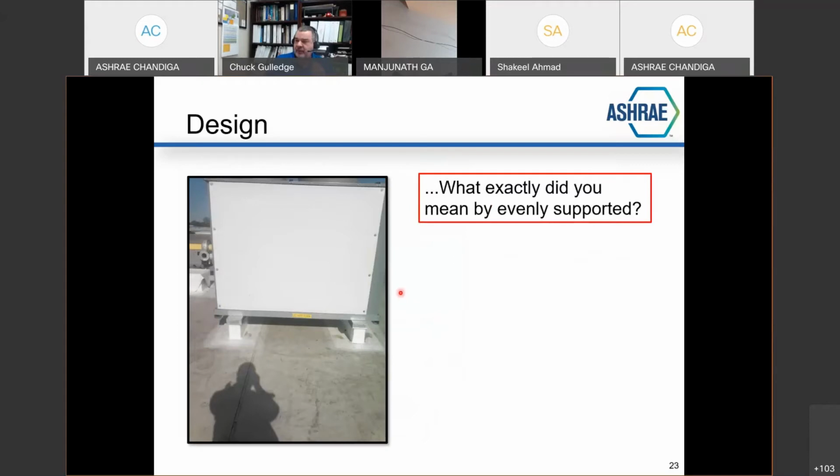This really happened. This is a condensing unit. This has a protective barrier over the fins on the condenser coils. Look at these roof supports. These should be lined up where the equipment is designed for the point loading to take place. These got installed in the wrong place. The roof got repaired, flashed in, the equipment got lifted up in the air and set down, and people were standing around going, well, why does it look that way?